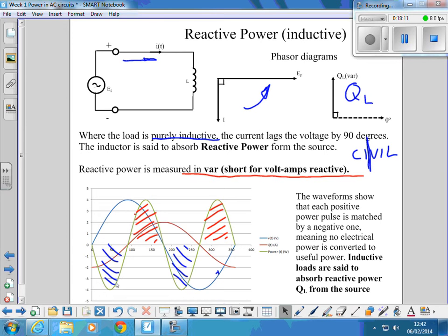Say, for example, you're using that coil to do some mechanical work. Is that going to cause a phase shift? Say, for example, in a solenoid, would that cause a momentary phase shift? If that coil is what we're modelling here, an absolutely pure inductor, i.e. Henrys only and no ohms, which is not achievable in real life, then you would get a 90-degree phase shift between voltage and current, as shown on this diagram here.